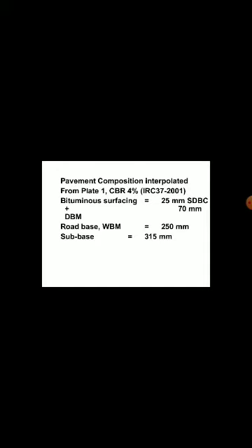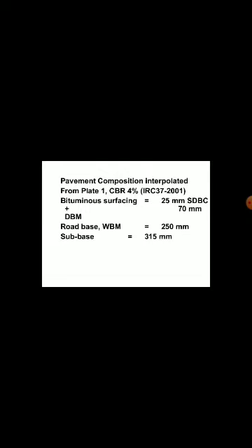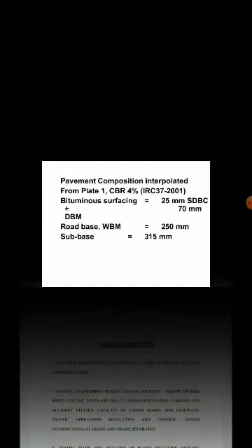Then the pavement composition interpolated from plate 1 for CBR 4%: bituminous surface is 25 mm plus 70 mm, road base is 250 mm, and the sub base is 315 mm, which is on the ground, followed by the road base of 250 mm.